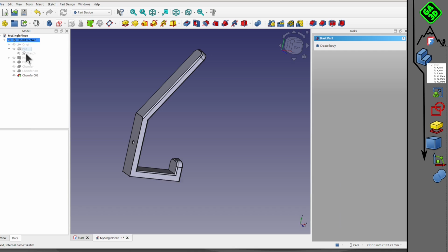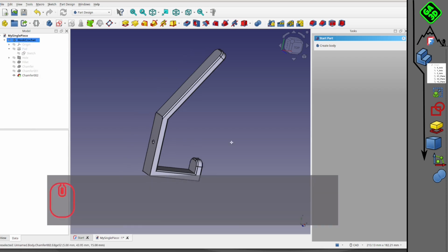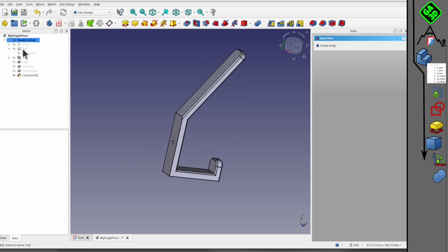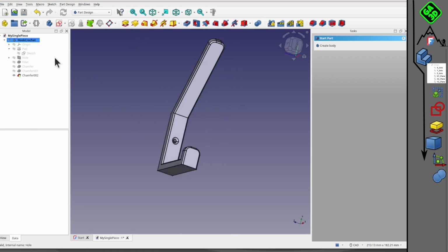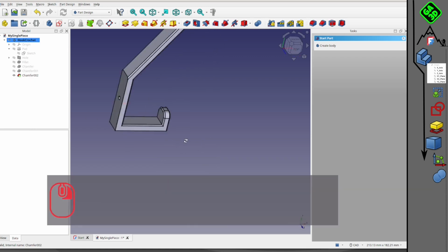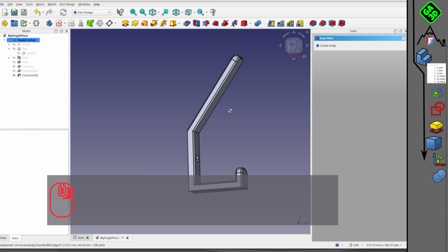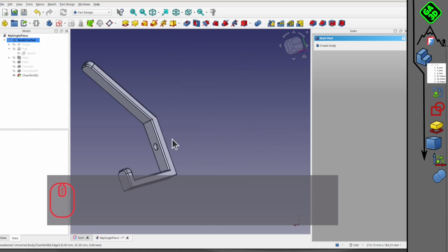Often, it will be with the extrusion function or with the revolution function. And then we have secondary operations like piercings, adding fillets and chamfers. And then, here's your piece, it's over. So that's really the typical workflow of a single piece that is sufficient in itself.